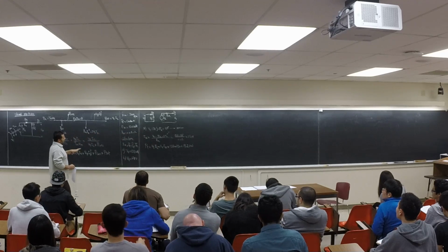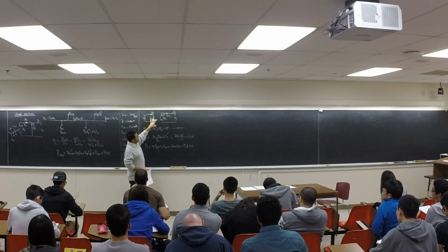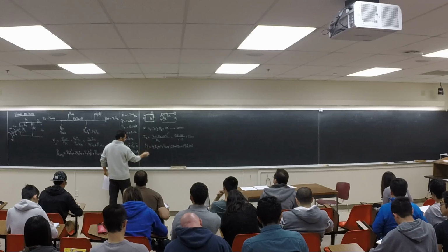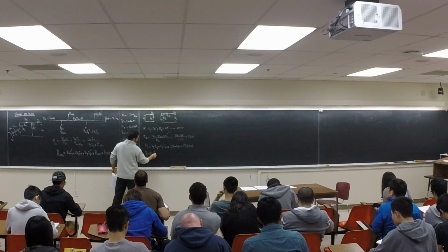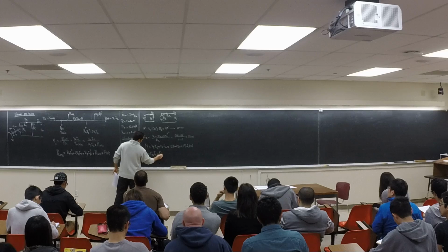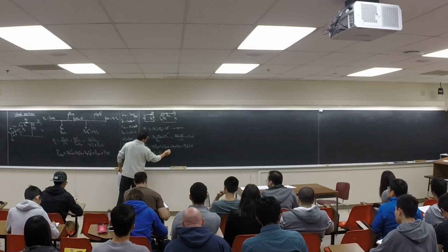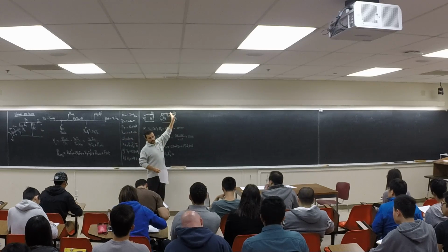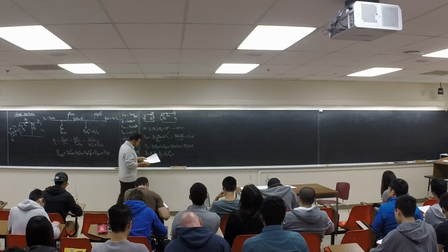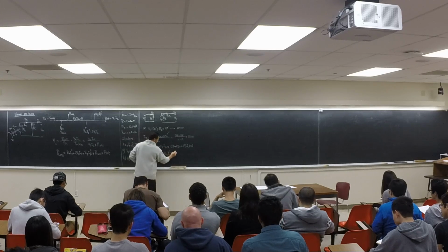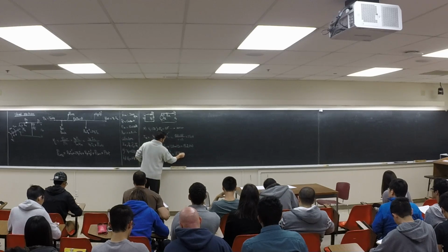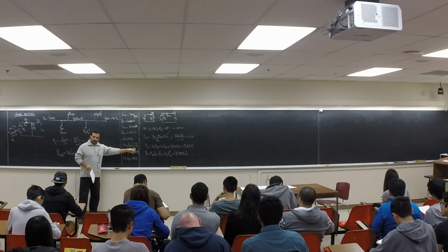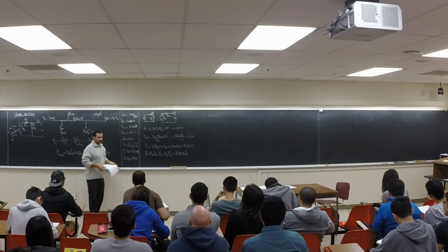Now, how much is the PE, P electrical? You can say EA IA, or you can say PT minus RA IA squared. Either way, the power coming in minus the loss you have here is going to be here. If you calculate this one, it is going to be 18.705 kilowatts. The last thing is the developed torque. How much is the TE?